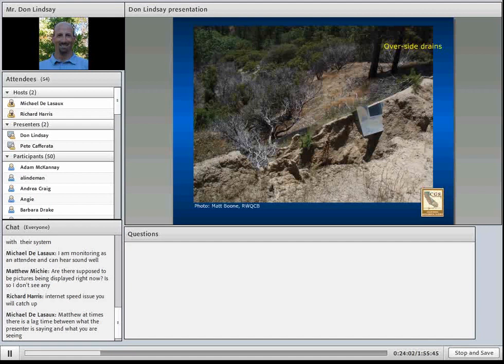There is a risk that these drains can fail when runoff is diverted away from the inlet. They become plugged with debris, damaged by equipment through maintenance operations, or are overwhelmed by flows. In this photo, you can see how the inlet structure has a prefabbed cutoff wall to reduce the potential of piping and scour beneath the inlet.